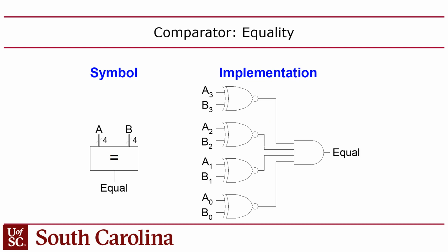How about comparing two signals? Well, this is what the book says to do. The book says that you can do an XOR gate between each pair of bits when you're comparing for equality, and then you route all the outputs of those into a big AND gate. But that's one way to do it. The problem with that, though, is that this AND gate is going to be really big. It's going to have a lot of inputs, which, like I said, will get broken into smaller gates when you synthesize it. But another way to do this would be the way we do it in class, which is to subtract A and B. Of course, even then, after you subtract it, you have to put all the output bits into an OR gate to make sure they're all 0. So this architecture might not be that bad.